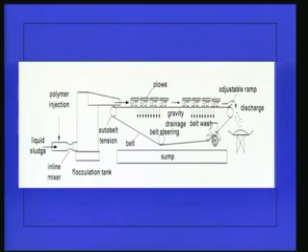We have seen in detail what are the different processes we have to adopt for the solid stabilization. We have seen the flow diagram. So preliminary treatment is required, then we have to go for dewatering. The reason is the water content in the sludge will be very high and solid concentration will be less. So definitely it will be increasing the volume of further treatment. So once the dewatering is done, then we can go for stabilization.